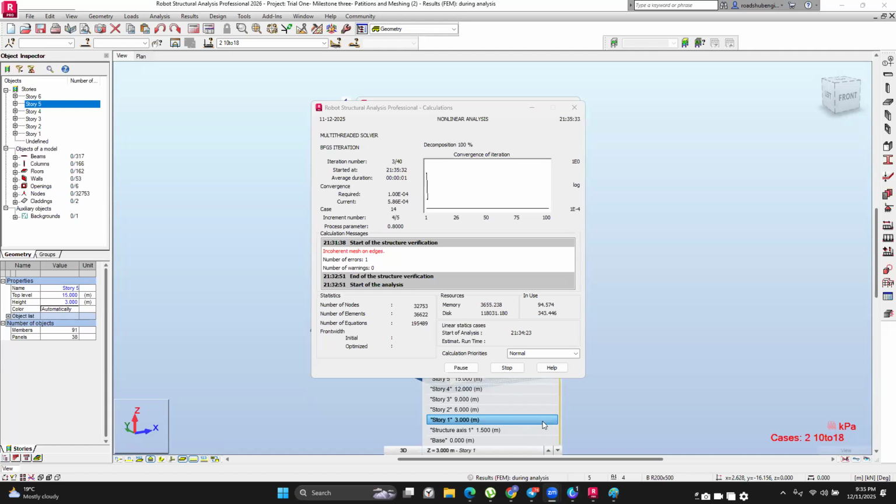Now, when we fill the space with soil, the active pressure will be acting horizontally, which is from inside the basement to outside of the wall. But now when you see the load symbol of how the varying load is being applied, it's like the varying load is acting from the outside, pushing the wall inside.